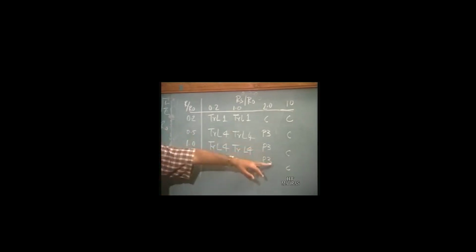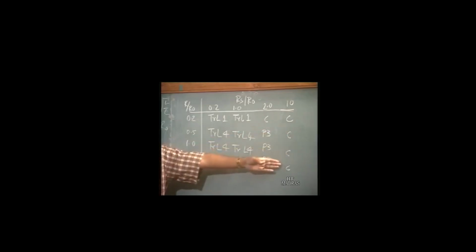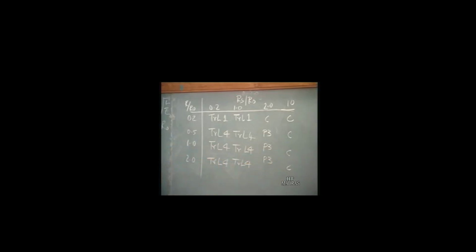So when it is possible to get the same results using just a lumped capacitance, it would be a waste of time to go for transmission line models. So this capacitance model would suffice. When we do an analysis, we have to look at the particular situation and see which model would give us the best results in the shortest amount of simulation time.